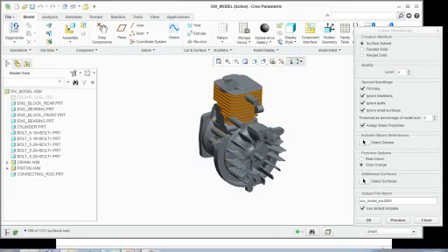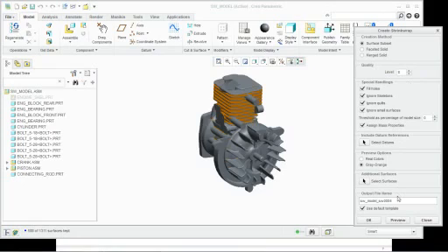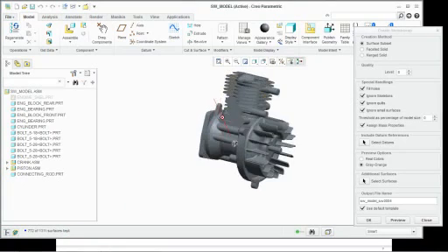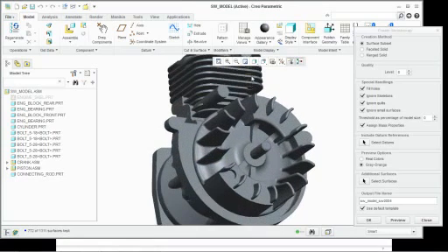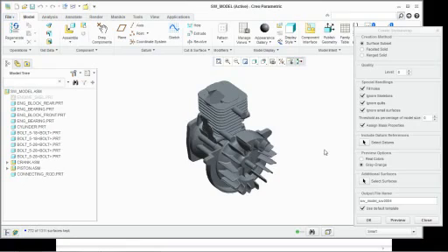So if you notice down here at the bottom left, 588 of 1,311 surfaces have been kept. If I change that level, let's say we'll change it all the way up to 8 and click Preview. Notice it takes a little bit longer to think about it. It's calculating. And now notice I have very little orange. If I look up at an angle, I can see some of the holes. There was a hole through there that's been basically eliminated.